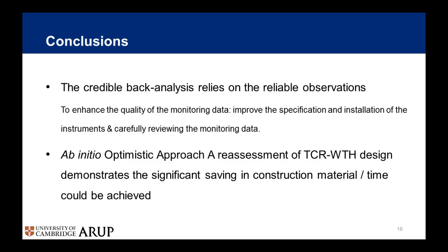Yeah. So, this is just my conclusion of this reassessment. Basically, the back analysis is the key of the observational method, but a good back analysis depends on reliable observation, and it is necessary to improve the quality of the monitoring data, which includes a better specification and execution of the installation of these instruments, and reviewing the monitoring data properly. And the last one is the ab initio approach A. It's showing it can significantly save the construction cost.